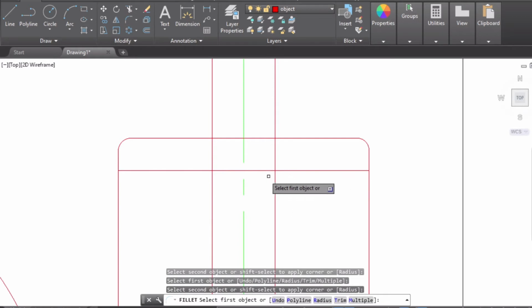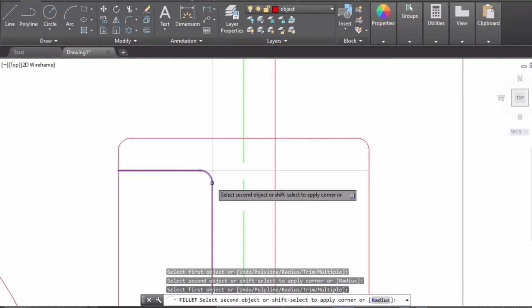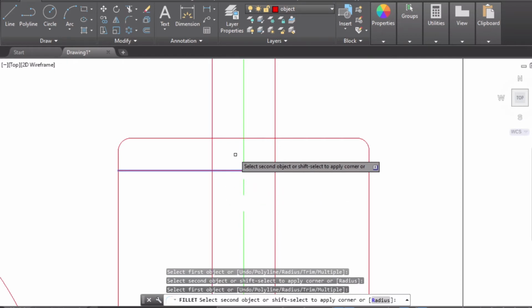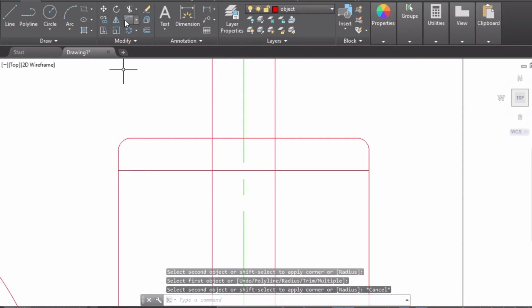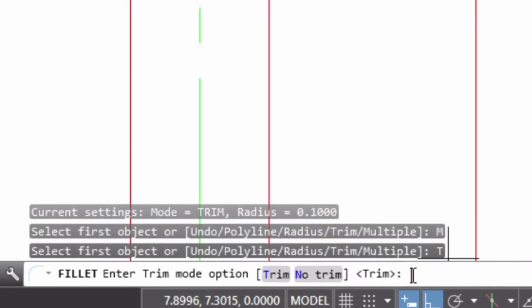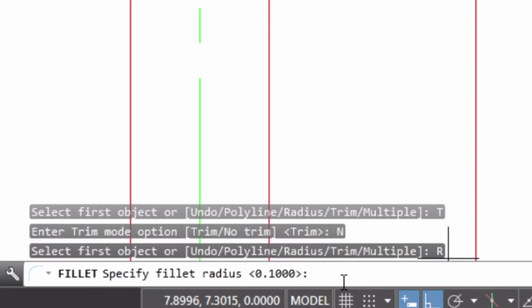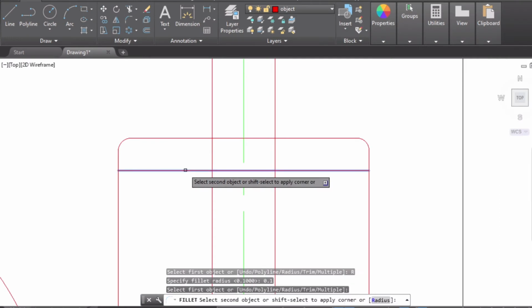Now what happens if you make a fillet with the same method over here, it's gonna delete the remaining, but actually we want this line. For example, let me show you. If you select these and these, it will delete the entire line that goes towards the right, but actually we want that one. To avoid that situation, what you can do over the fillet option, when you take fillet multiple in trim, and you select the trim option, choose no trim, and now you can enter radius 0.1, enter, and you can select this side and this side.